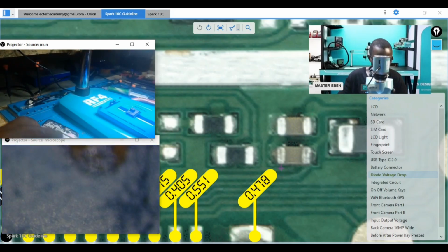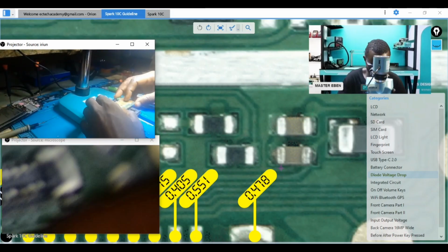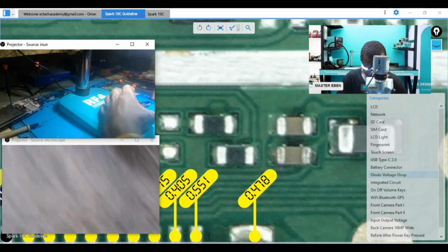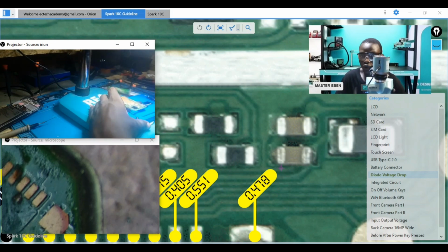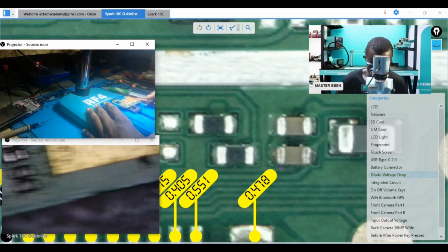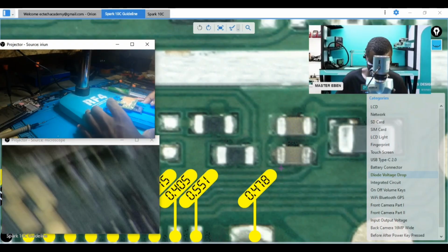You know what, let's try to check the diode mode of that leg. I forgot to check it. So let's try to check if the condition changed. We're supposed to have OL for that pin. So after removing the resistor, let's try to check if the condition changed.